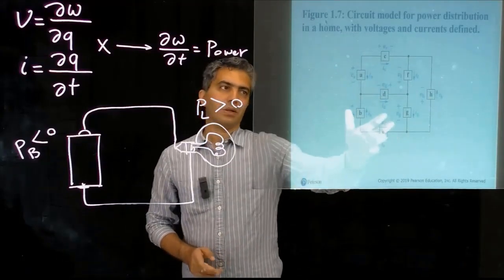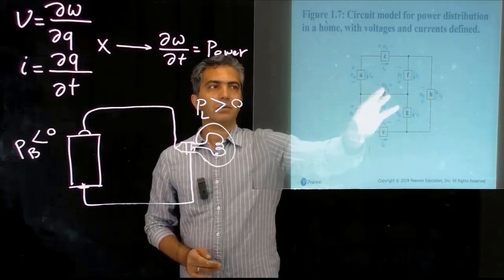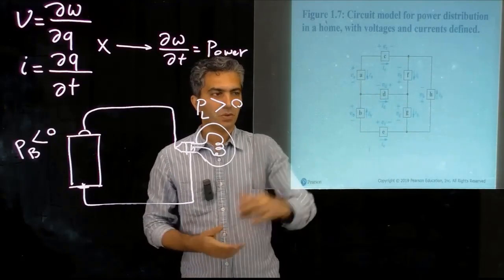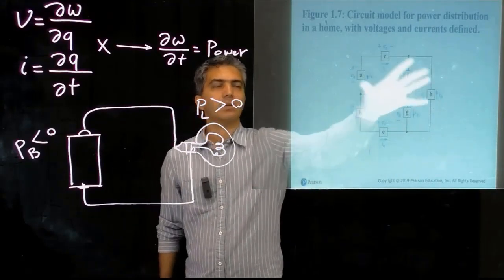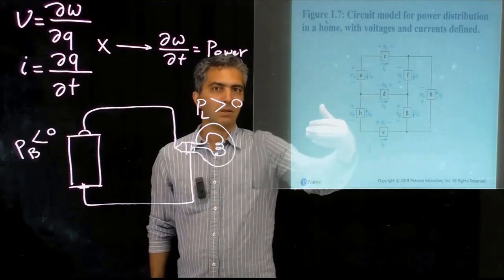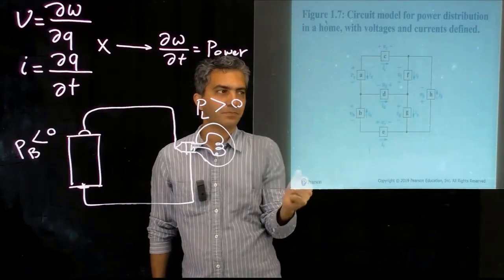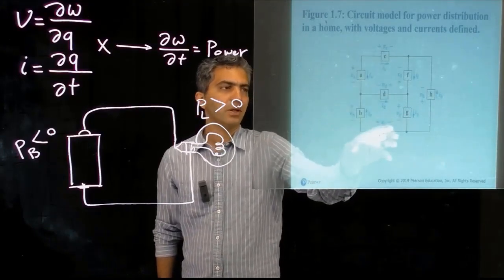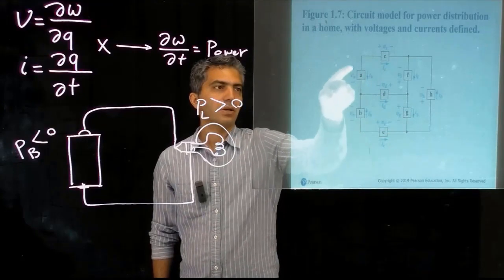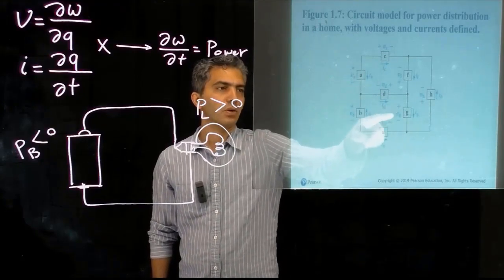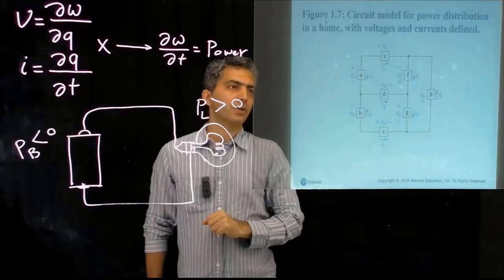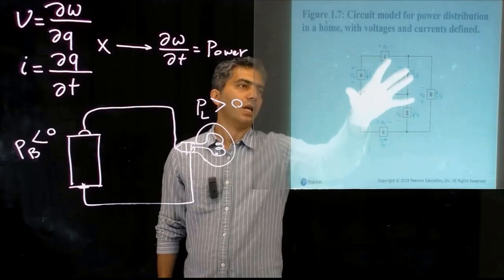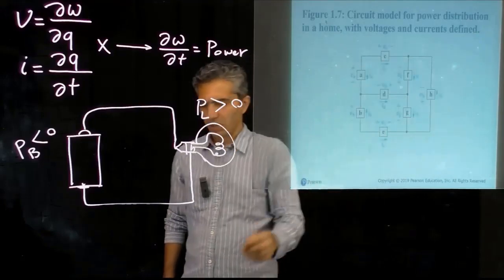And that's one way to calculate the distribution of power within a system, to use the zero sum of all the powers as a rule for the analysis. So then again, if I start basically labeling the circuit and assuming certain direction for the currents that are passing through the components, and assume voltages across by putting positive and negative sign, I can start calculating the power for each one of these components.